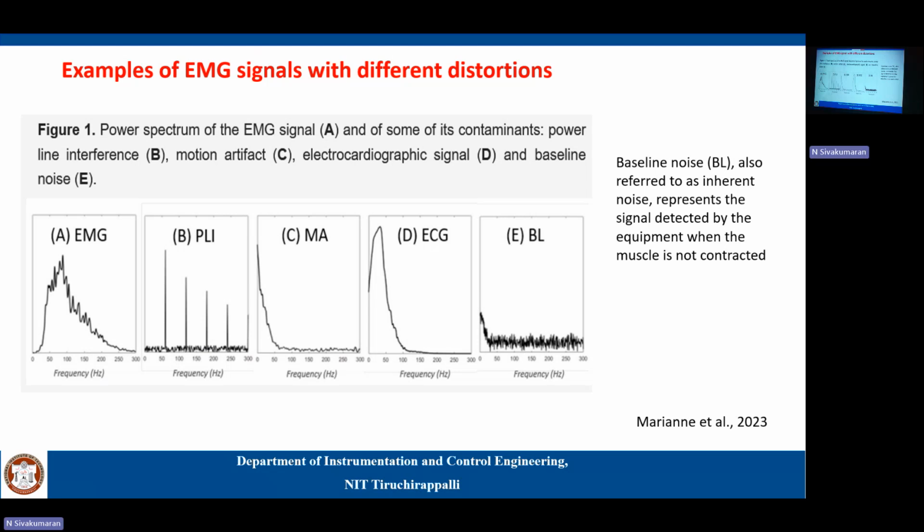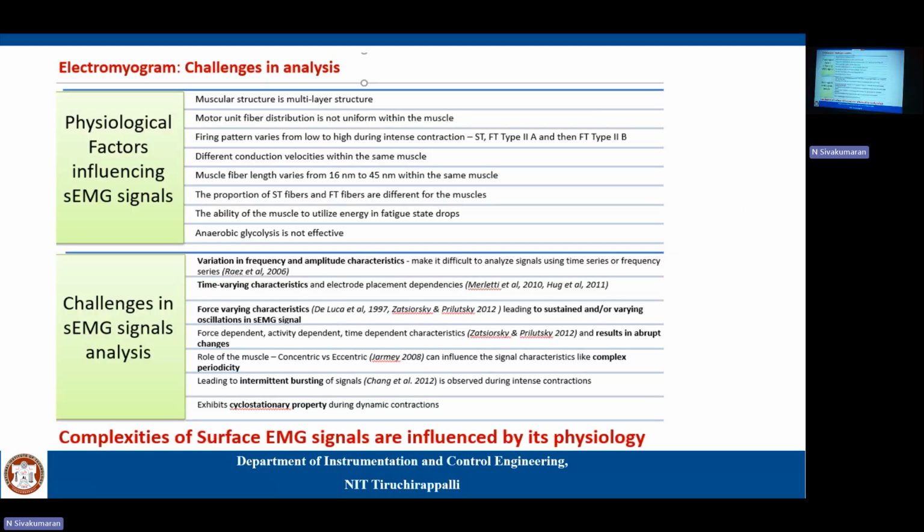So in this case, I see peaks at 60, 120, 180, 250 Hz. You have to design your filter such that you are removing all this data, all this noise. So these are some of the challenges.